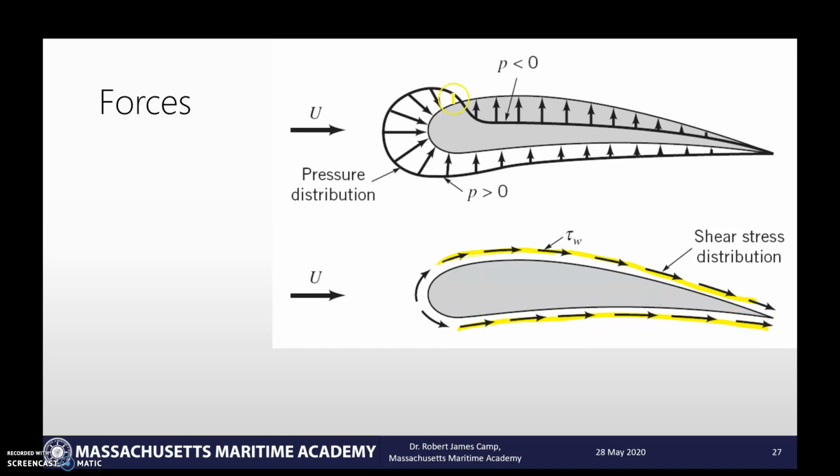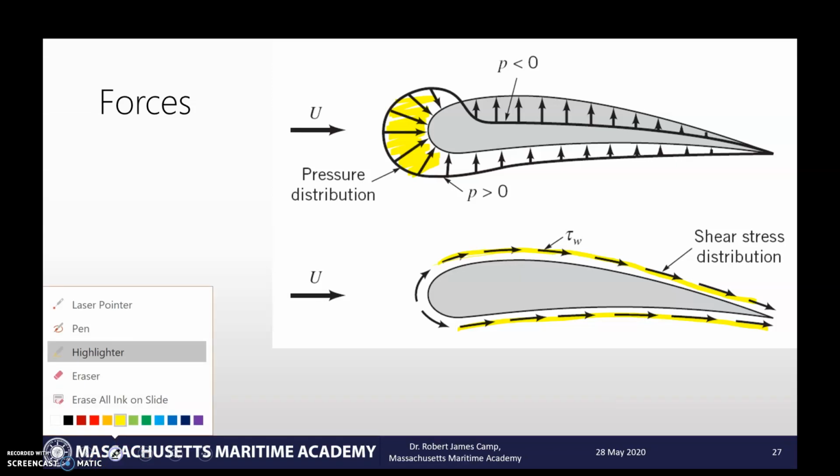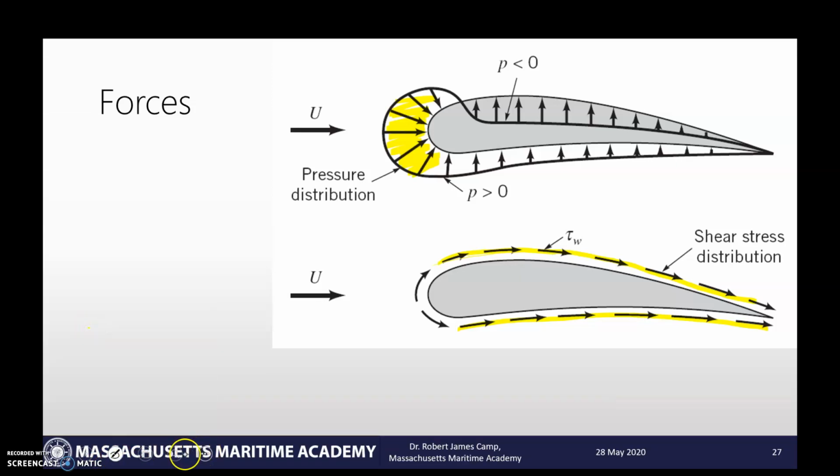And then the drag force from the pressure is going to be all this area here. So everything else is going to contribute to the lift of the plane, or the airfoil or hydrofoil. And so the coefficient of drag can be broken up basically into these two huge components. We can look at what we call the friction drag,